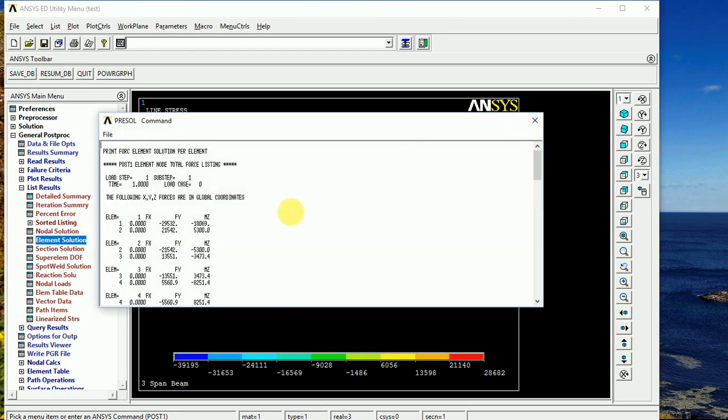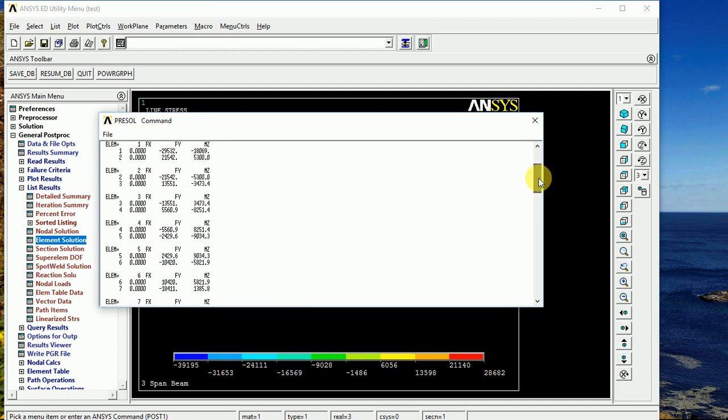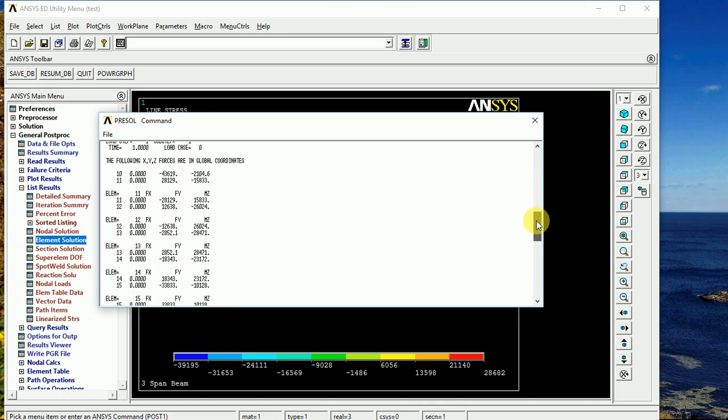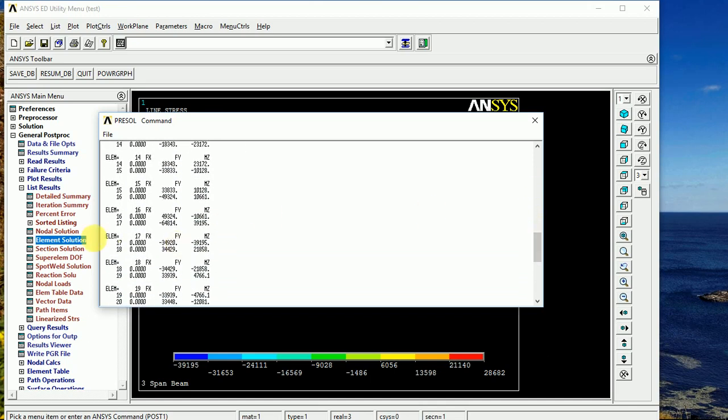Now we can see here the element number up here, FX direction, look, there's nothing going along in the axial direction, so that's fine. But these FYs are essentially vertical forces across a section, so they are your shearing forces, aren't they? Okay. So if you look, let's look at element 16, and I'm going to look at node 17 because that's where the support is.